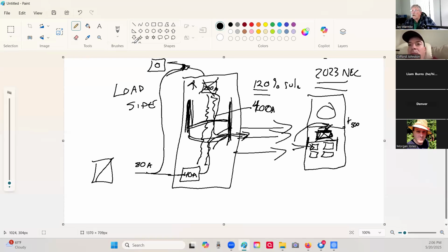If you put in or have someone put in a new emergency disconnect and that now becomes your main, they want to make sure that you've separated your neutrals and your grounds in any subsequent boxes. That's an electrical thing. It's not really a solar thing. The electrician should take care of that, but you should be aware of it, because you're making yourself perhaps a problem.